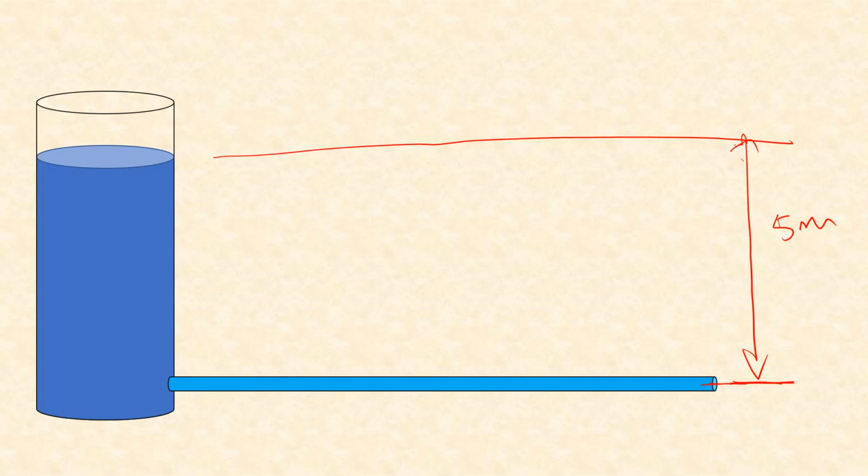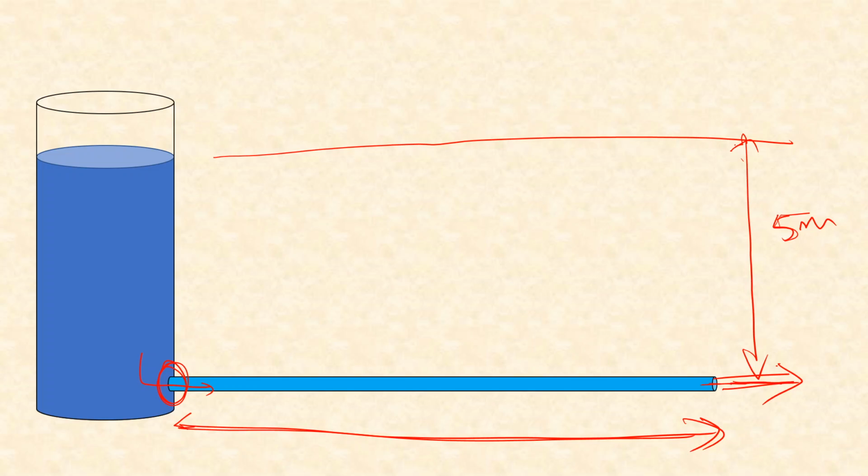and so in this case, what will be the head loss? Now the head loss will be this total 5 meter, because after entering this pipe it will lose some head here, some additional head while flowing through this pipe, and at the end it will have this velocity, but that velocity will again be lost into the atmosphere because now we are not storing it anywhere.